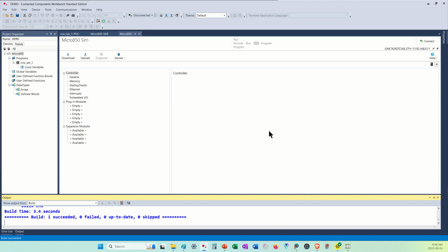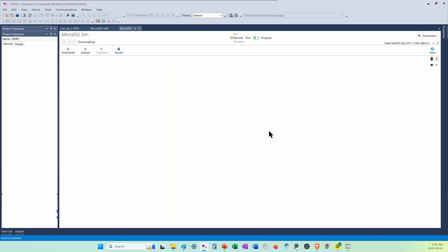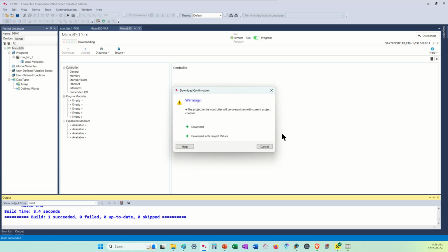And when it does the download, the first thing the program will do is it will try to build the logic. It's going to look at the logic and make sure there are no mistakes. It will not allow you to put self-destructive faulting logic into the processor. It's trying to save itself some grief and save yourself some trouble, and it builds it, tests it, and if there's problems, it'll have down here failed, and you'll have little red X's that, yeah, thank you very much for trying. We have some lovely parting gifts called try again.